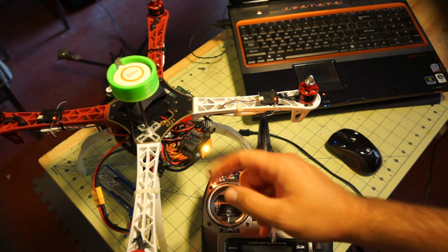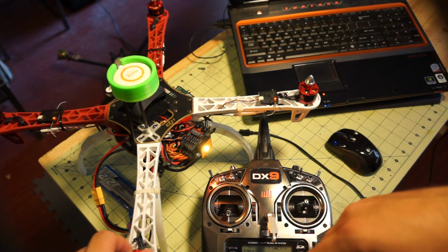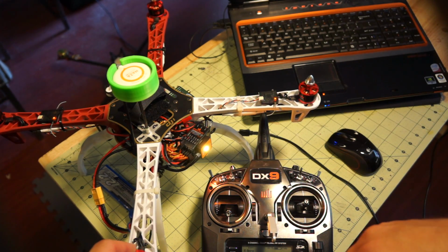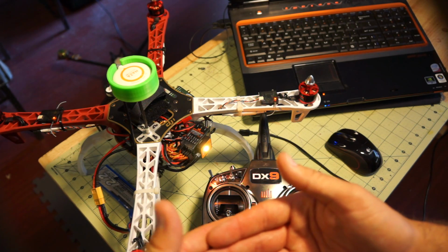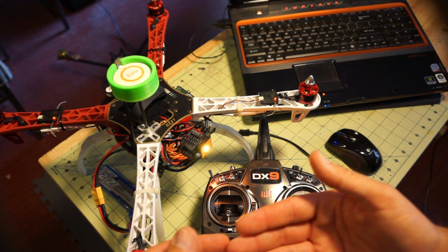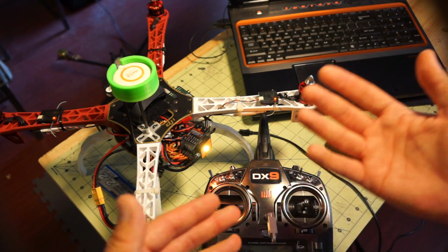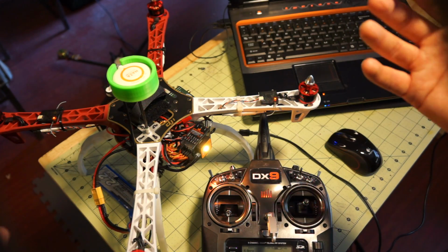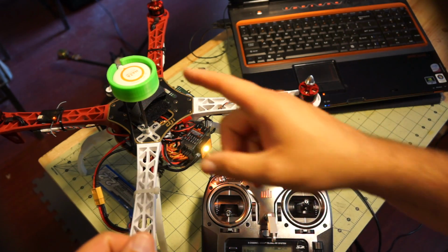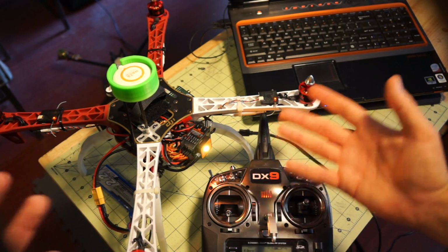If the LED starts flashing red, then you've got a bad compass cal. You need to redo it, and probably in another location. If you try to do that in an area that has a lot of metal on the ground, or if you're on top of concrete, there may be a lot of rebar in the concrete, you're going to get a bad compass cal every single time. So just make sure to try and do it in a nice grassy area with a fairly clear canopy, so you can get a good GPS lock and a good compass cal, and then you're ready to fly.